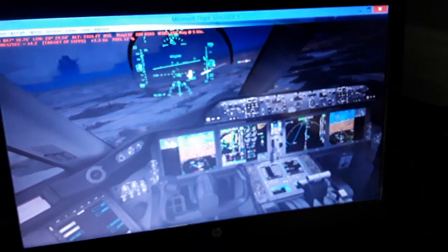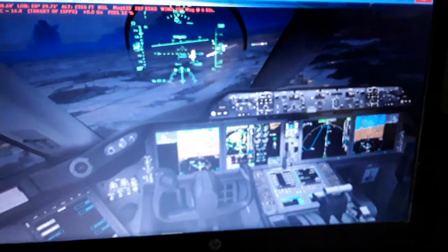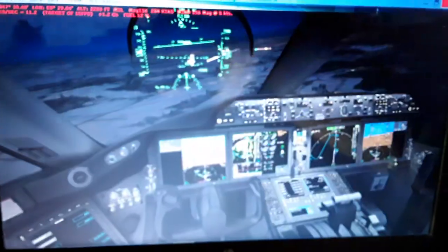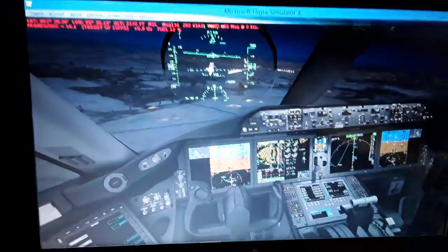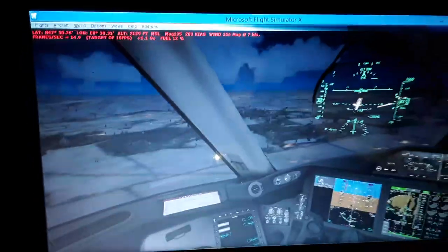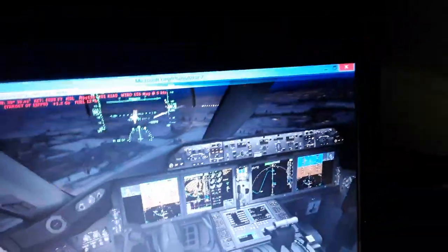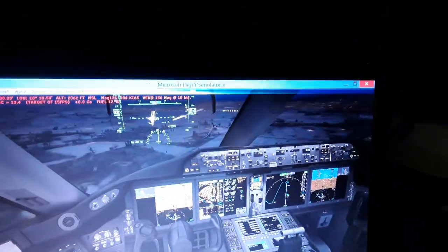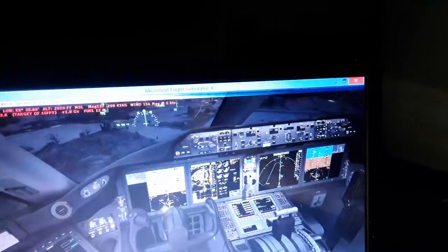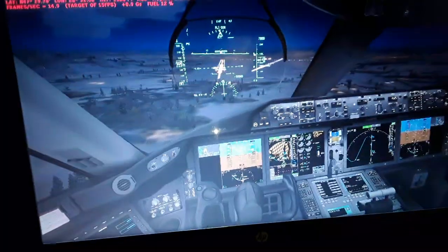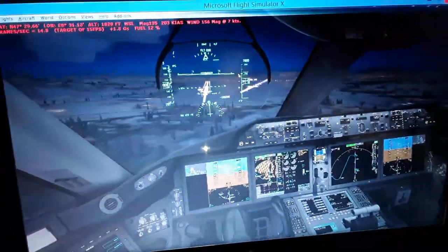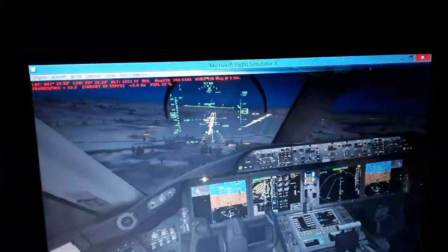So we are approaching for the landing. We have a few more seconds, as you can see. So we are in a very good position. Keep using cross controls because we have some wind gusts, side wind. Use also flaps 30 degrees over here. So we are very close for the landing, as you can see, aligned with the center line.